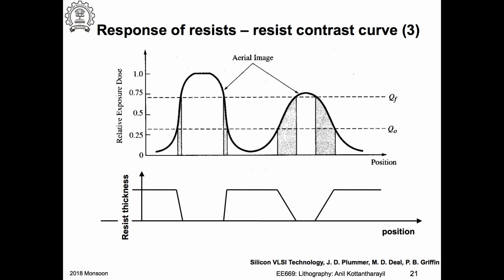Okay, so this is what we discussed, right? Suppose now I use this resist, can I do a good lift-off? So what is the next step in the lift-off? I deposit gold and it gets deposited on the flat surfaces, here, here, here, and so on. And on the vertical walls I don't expect any deposition, right?